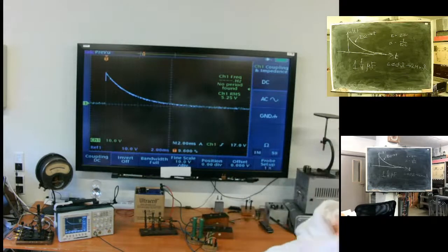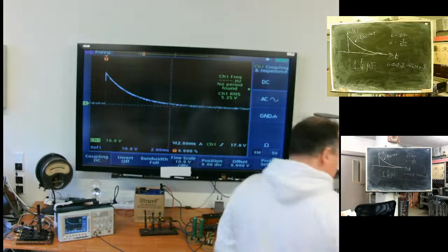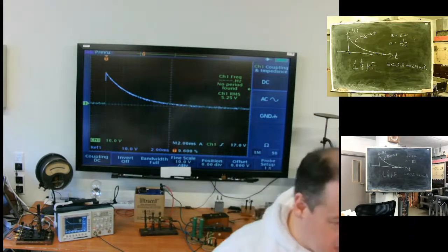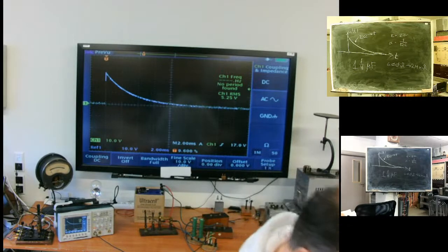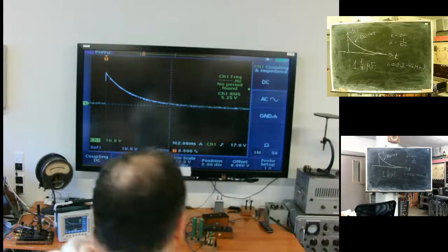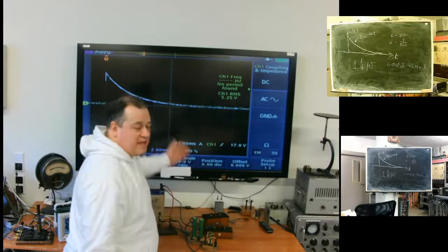If voltage or current repeats, no problem, we can decompose it as a Fourier series, as one ideal DC component and a set of ideal AC components, and use what we knew from the basics of electrotechnics. It's applicable, no problem. But this one is continuous, is determined, but never repeats.